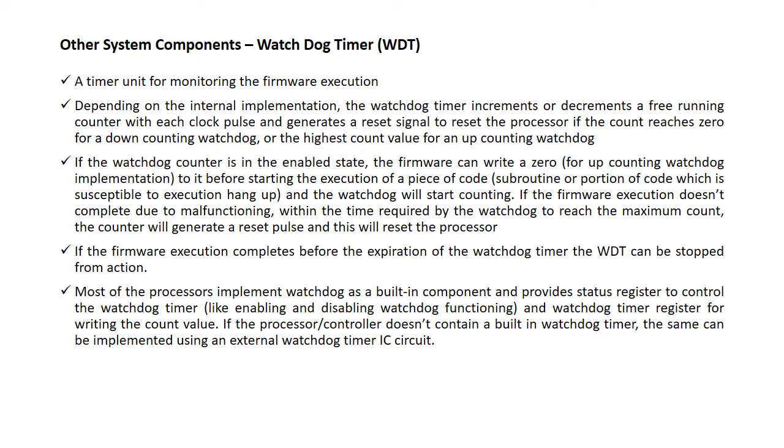If the firmware execution doesn't complete due to malfunctioning within the time required by the watchdog to reach the maximum count, the counter will generate a reset pulse, and this will reset the processor. If the firmware execution completes before the expiration of the watchdog timer, the watchdog timer can be stopped from action.